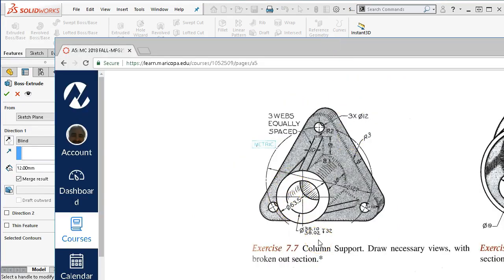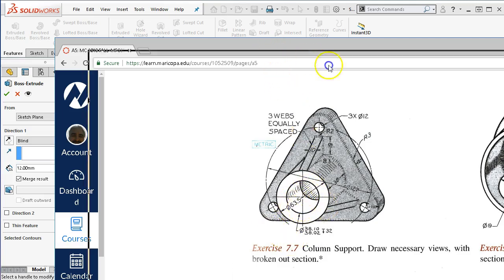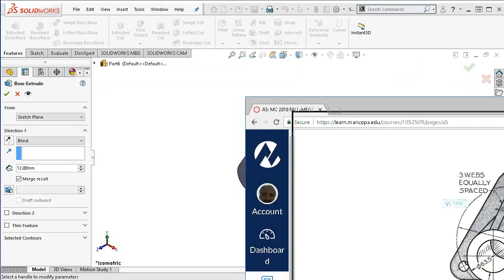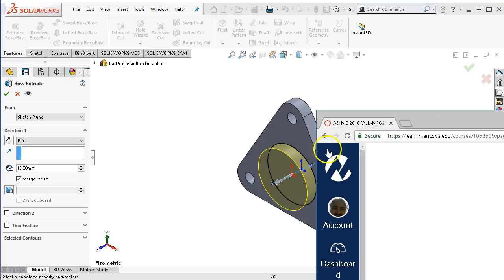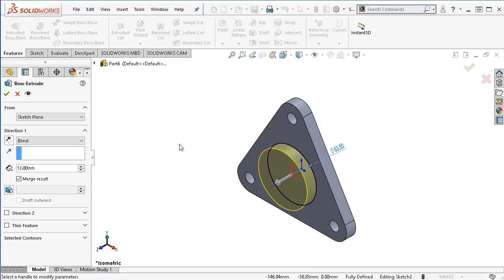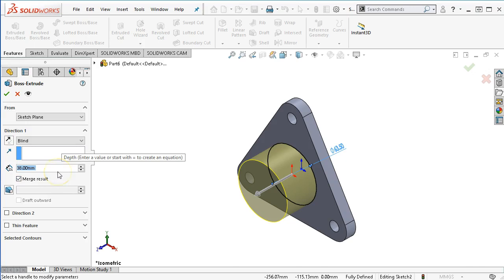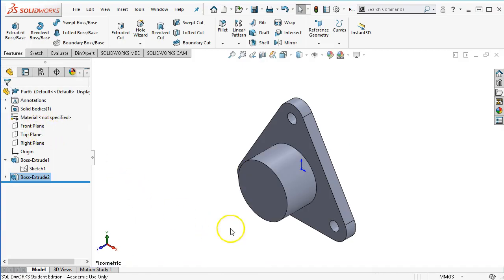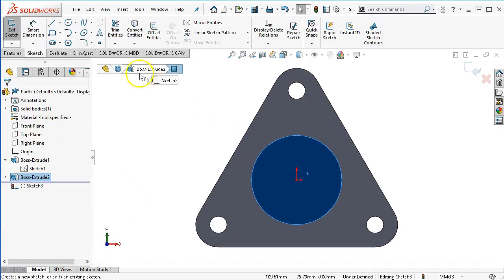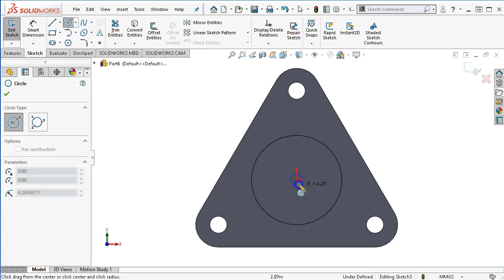And plus it has the limit dimension, so what they don't tell us is if they're going to include the drill, a drill point, or if it is going to be flat bottom. So the assumption is that it will be flat bottom. If we don't see a depth, it's assumed through. And if it's not called out with some kind of detail illustrating a drill point, we're going to make the assumption that it's flat. So 38 millimeters. Go ahead and accept. Open up the next sketch on the end face, it rotates into position.